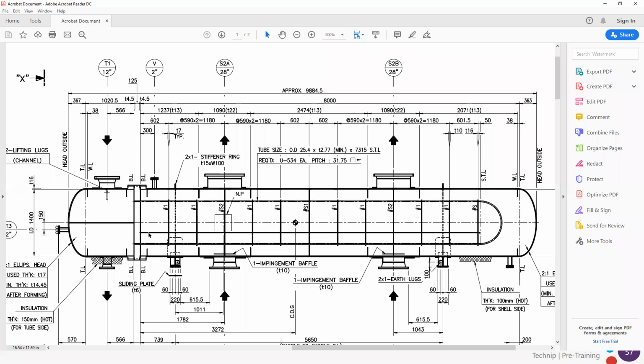Since we have MP steam, which is a clean fluid, condensing inside the tubes is better. In this case, we have supports instead of baffles. It means that the fluid is not redirected, because it enters and goes up. Baffles redirect the fluid, while supports only support the tubes.